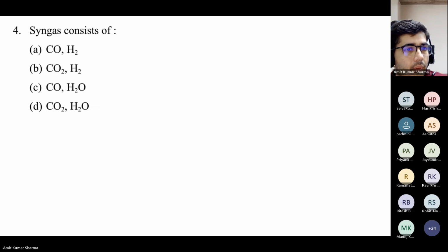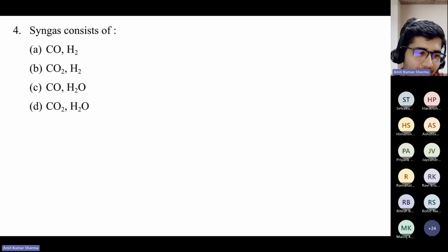By installing pre-reforming before a reformer, how much will the life of the reformer catalyst be increased? I don't have the exact number, but it is a good idea to have a pre-reformer. Otherwise, you will have severe carbon deposition.